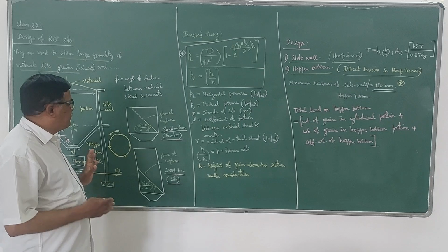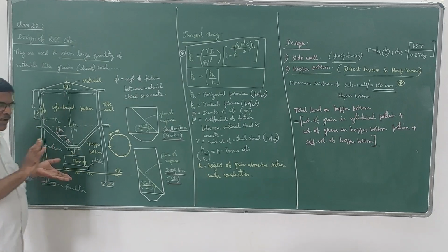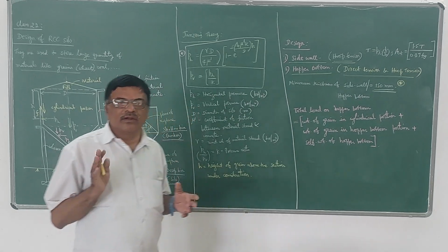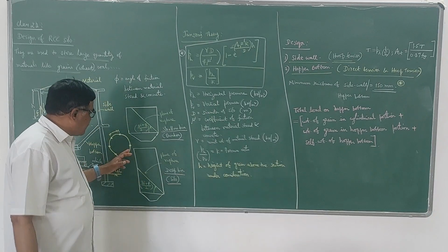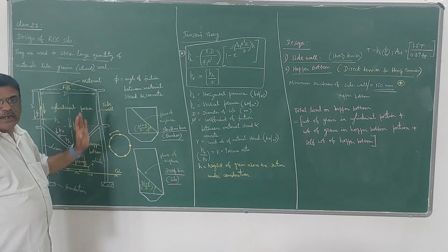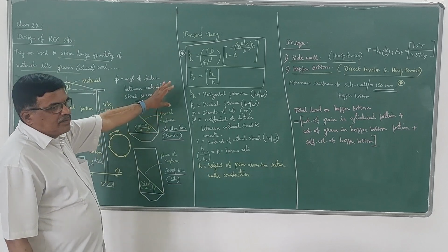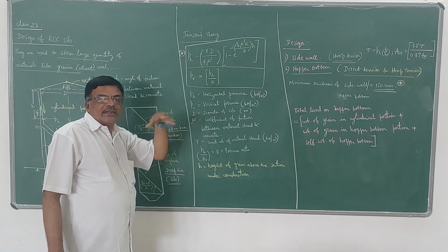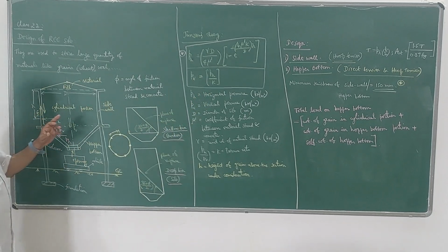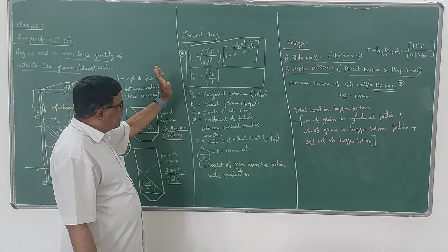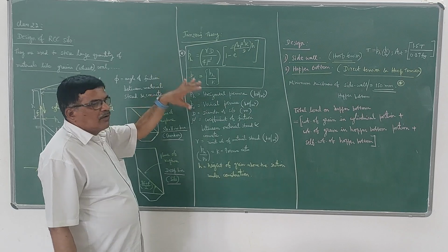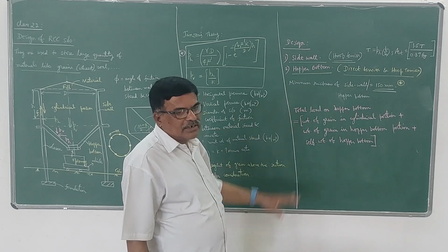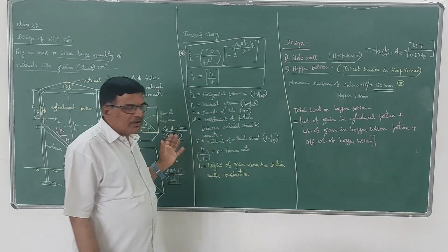So that means finally all the silos normally will be of cylindrical shape, that is circular in plan, whereas bunkers may be rectangular or circular. So the depth is more in the case of silos compared to bunkers, and usually the silos are designed based on the pressure criteria, considering the friction aspect also. So these two are the formulas you have to use by Janssen's theory. After getting the pressures, then we are going to calculate the axial tension, hoop tension as well as direct tension, and then we are going to calculate the required reinforcement.